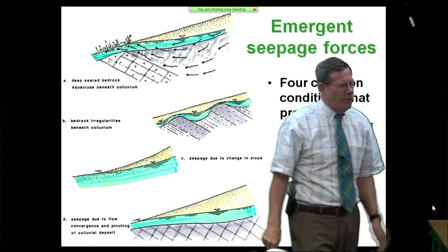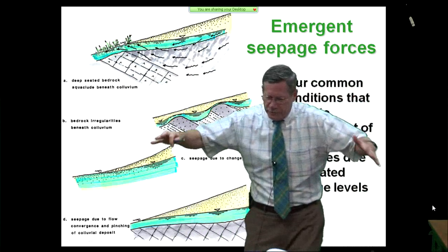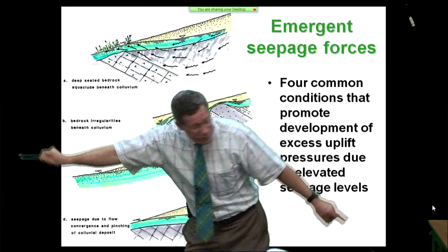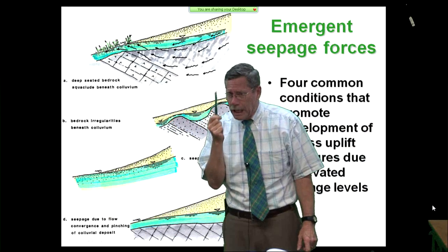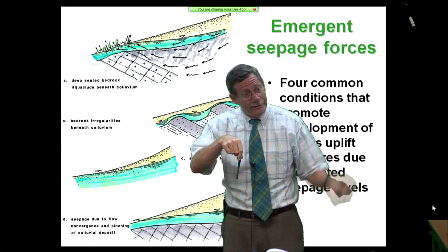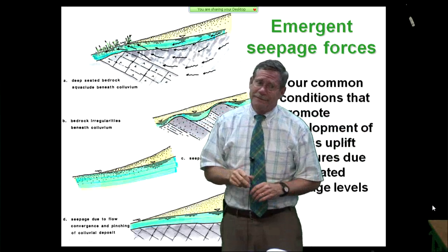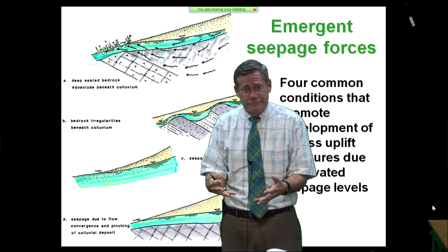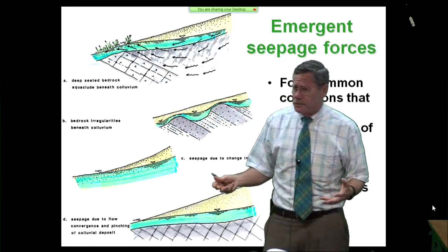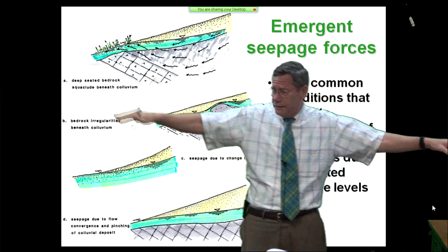That's a dead giveaway. If you see a bunch of water-loving plants right here, and you don't see them right over there and right over there, do some thinking. Ask yourself, why are they here and they're not over there and not over there? There's a real good reason for it. It's the accretion of subsurface flow. If it was structurally controlled, you'd see it all the way up and down the valley.